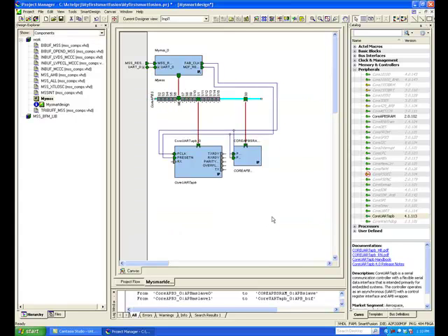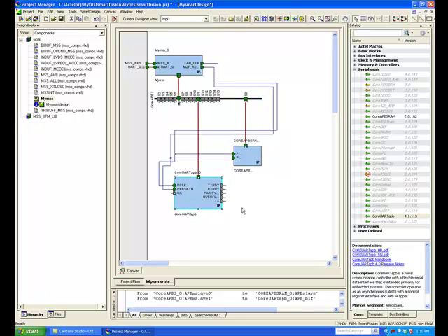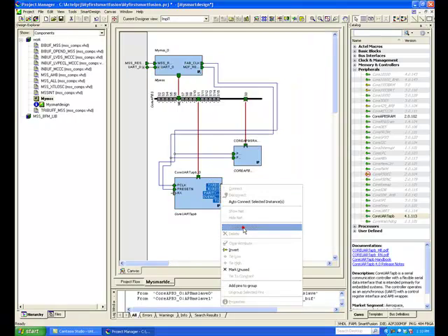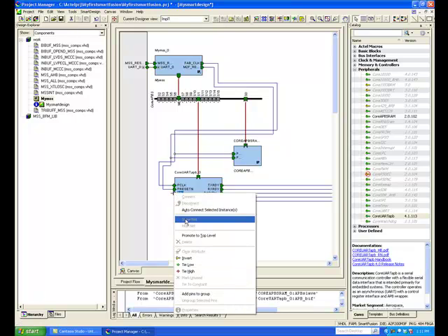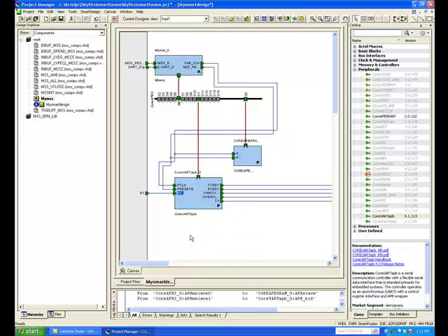Note that the key connections to the Core APB SRAM and Core UART and MSS have been made. Now, highlight all outputs of the Core UART by dragging across them, right-click, and select Promote to Top Level. Right-click the RX input on the left side of the Core UART and select Promote to Top Level. At this point, the logic design is complete.